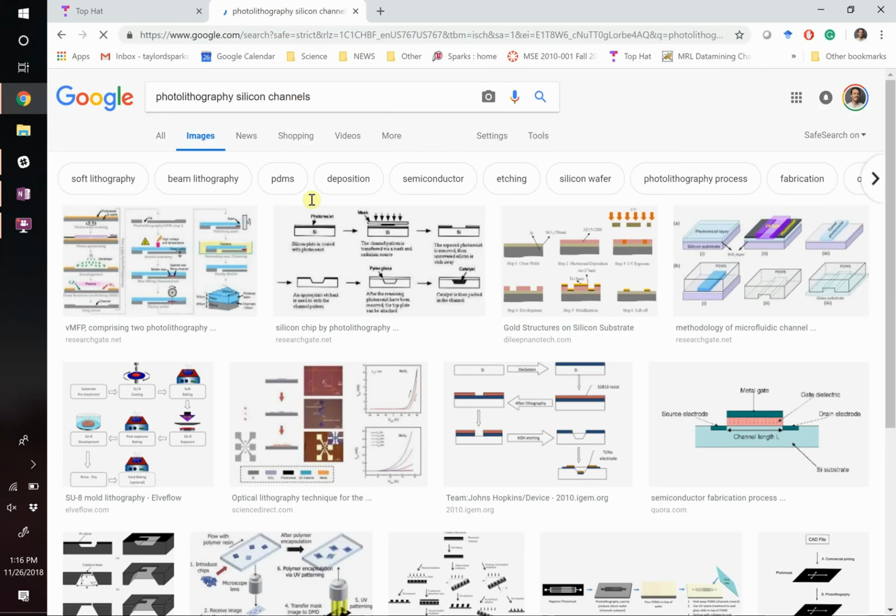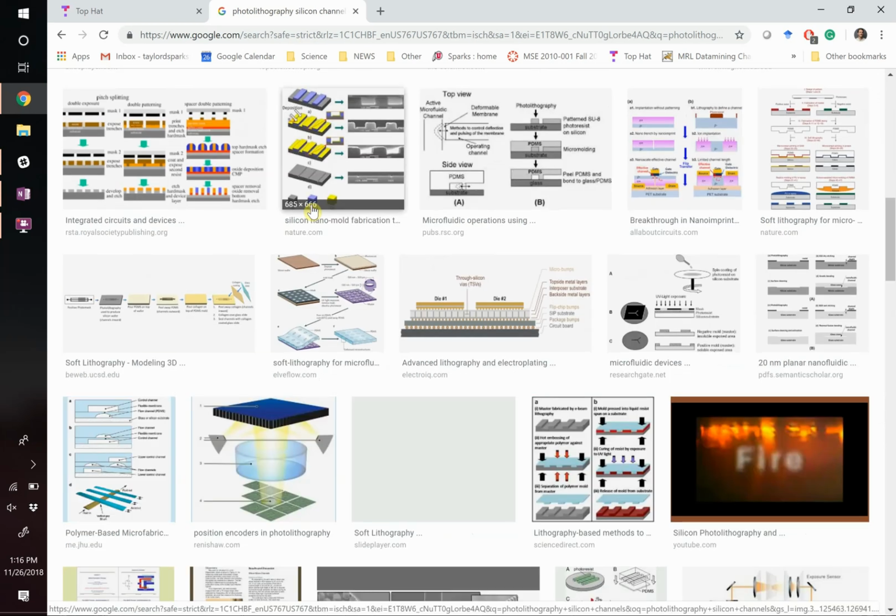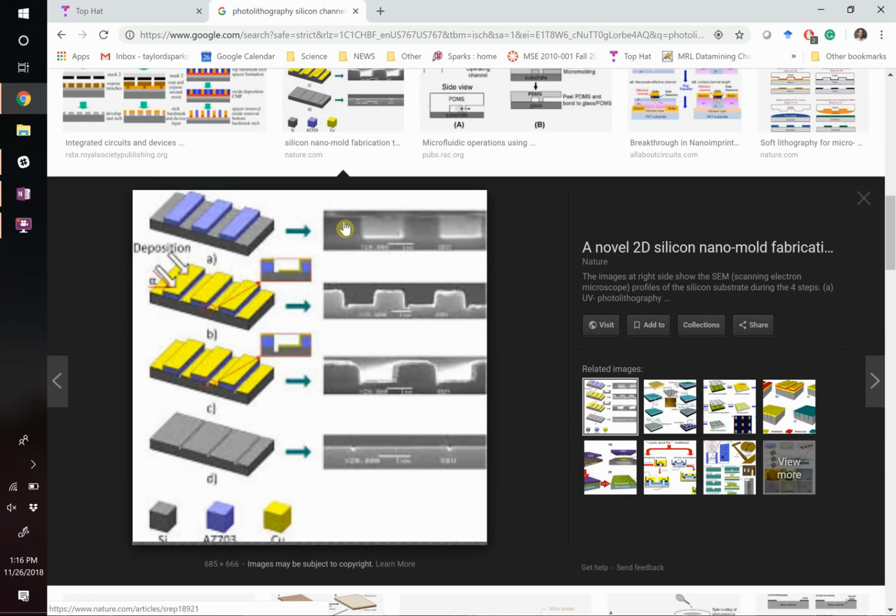What do we got? So you can generate very unsatisfactory images here. Something like this. This is what it actually looks like. Here's your photoresist, right? You wash that away. Now you've got this channel. You could put your silicon here, or your dopants here in these channels. And now you have whole channels running through your material that have different conductivity than the stuff around it. And this is how they start making really interesting electronics devices.